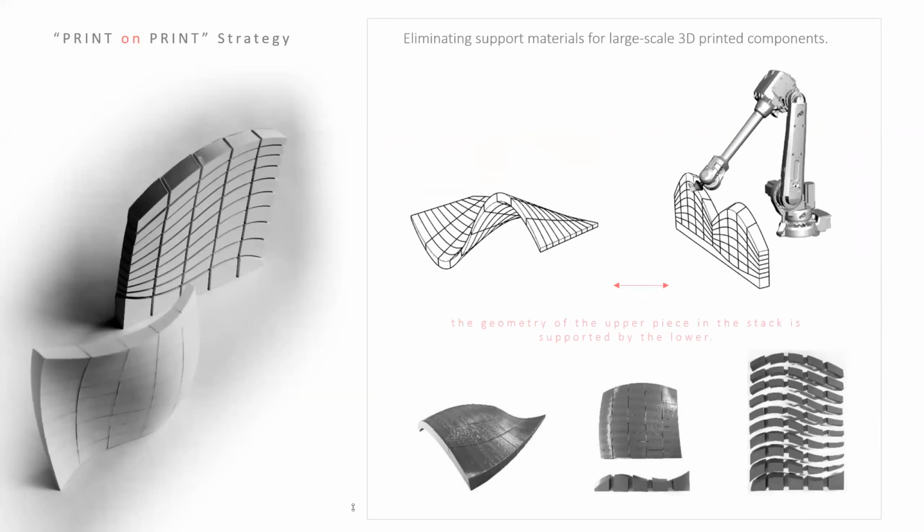But print on print is more about this: if you want to print this surface, it needs a lot of support system and scaffold under that. But if we break the geometry into components, where each piece is going to be the scaffold for the next piece, and then you can separate them, then you can have more complex forms without scaffolding.